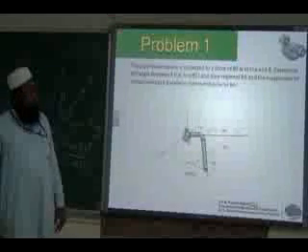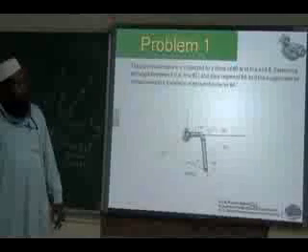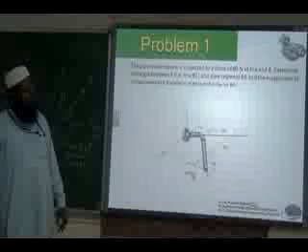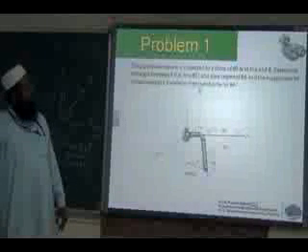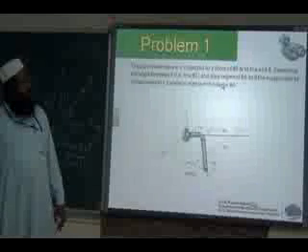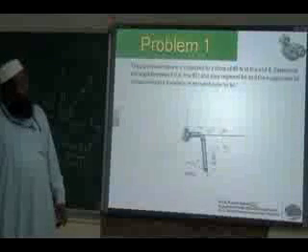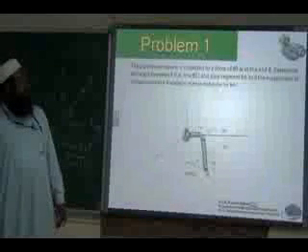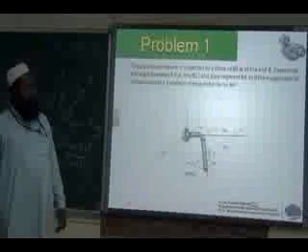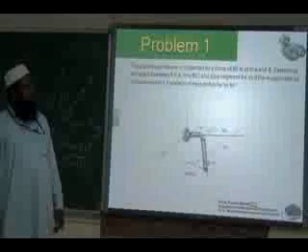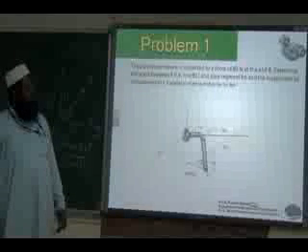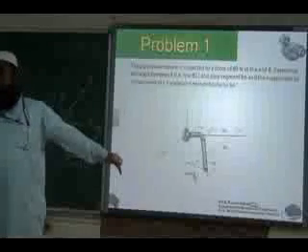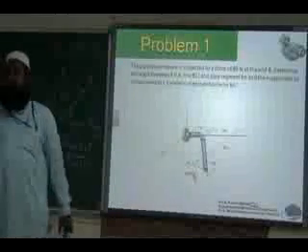Say you are given a pipe. The pipe is fixed to the wall. It is acted upon by a force of 80 Newton. You are asked to find the components of the given applied force parallel and perpendicular to the pipe segment AB. So first, as usual, we have to find the position vector for AB, and because only the force magnitude is given, first we convert the given force into Cartesian form.